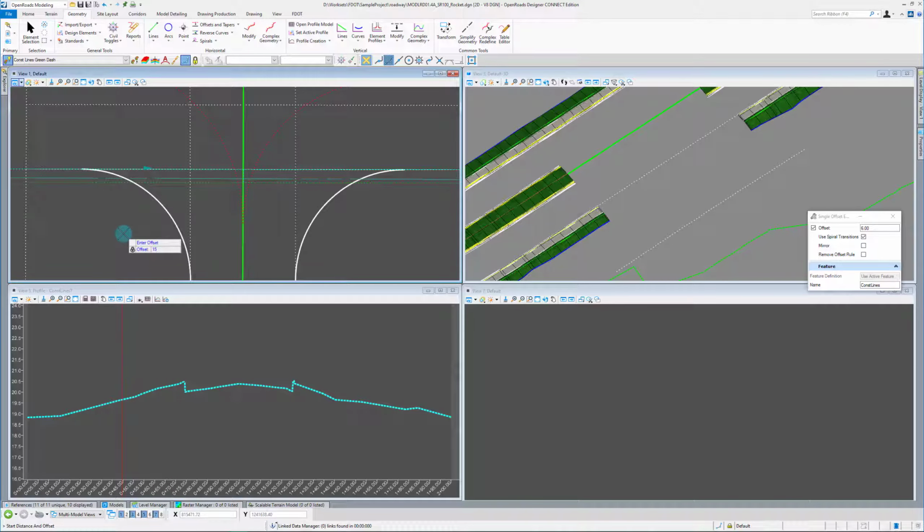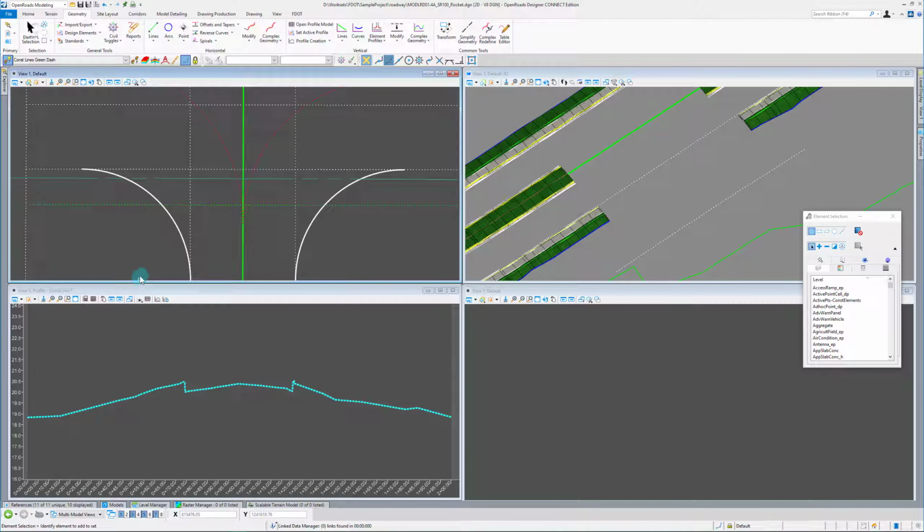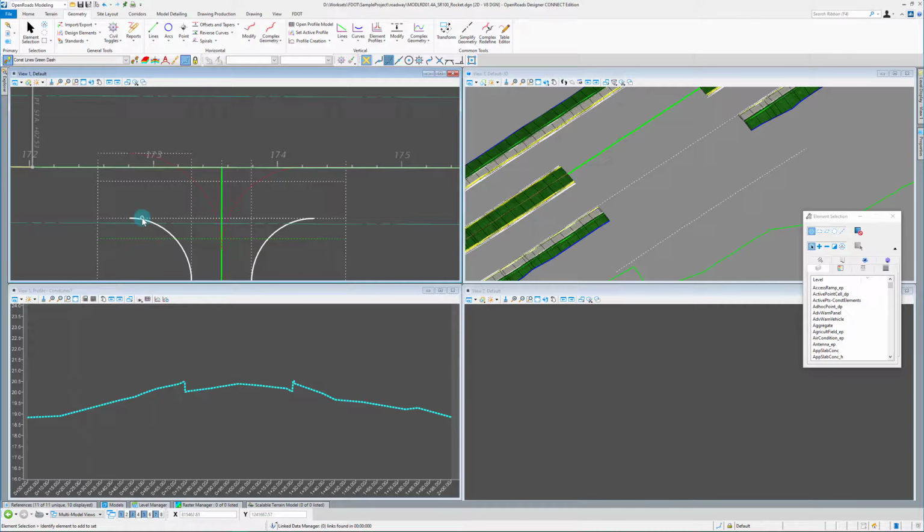And let's just say 16 feet for now, just a guess based on where my curb ramps typically end up. So we're probably going to have a curb ramp that goes across the street here, because this is a signalized intersection. We're going to have crossings at all four legs. So we're going to have a curb ramp that goes here.